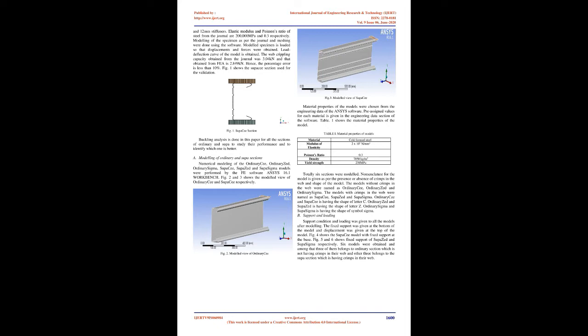Cold-formed steel is used as flexural members in lightweight steel construction. They are structurally and cost effective, thus their thin-walled members are used in low and mid-rise building construction. There was a rapid growth in the usage of CFS in buildings because several innovative and structurally efficient CFS products were easily available. Advantages also include lightness, high strength and stiffness, ease of prefabrication and mass production, fast and easy erection and installation, etc. Products of cold-formed steel are available in different shapes and sizes.